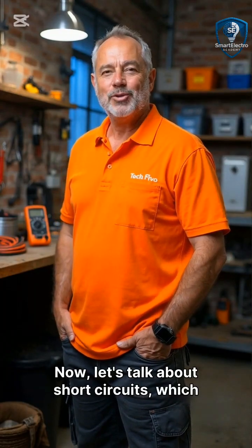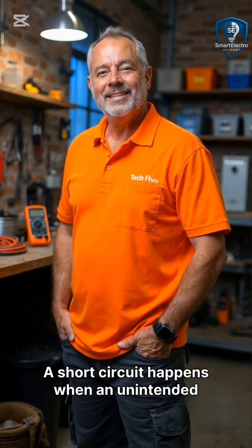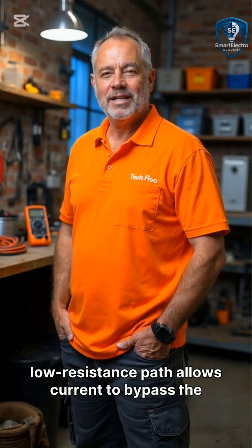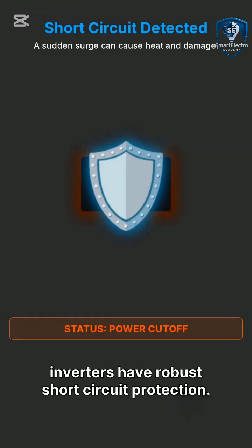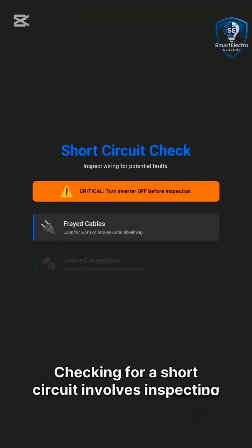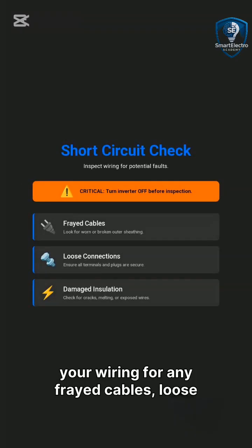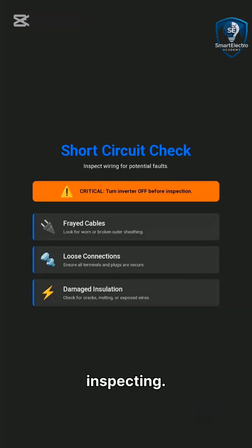Now, let's talk about short circuits, which are often more serious and require careful attention. A short circuit happens when an unintended low-resistance path allows current to bypass the normal circuit. This sudden surge of current can cause significant heat and damage, which is why inverters have robust short circuit protection. It's designed to instantly cut power. Checking for a short circuit involves inspecting your wiring for any frayed cables, loose connections, or damaged insulation. Always ensure the inverter is off before inspecting.